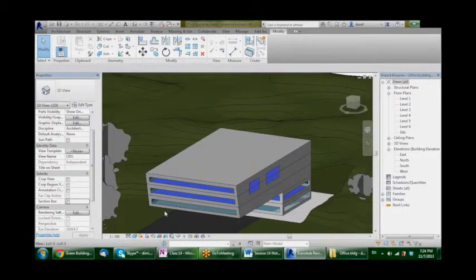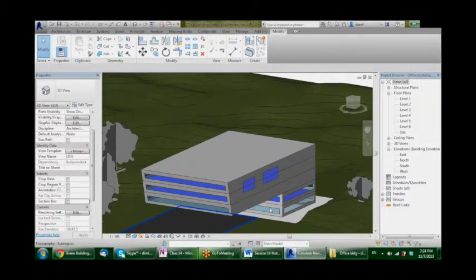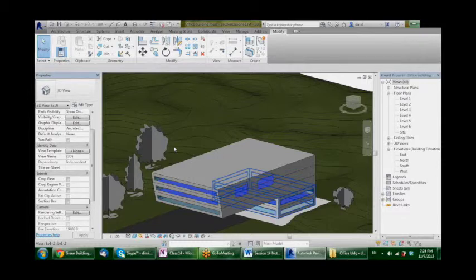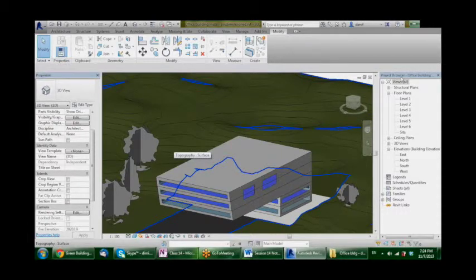So these are the basics for mass modeling for energy analysis. So I'm going to now take it back to the analysis that we can perform with this tool. Last time I showed you what you can do within Revit. So under the Analyze tab, Energy Analysis, you can refer back to your simulations and the results of your design by hitting this guy over here, Results and Compare, which basically summarizes all the runs you did.